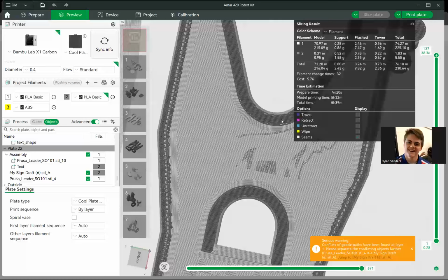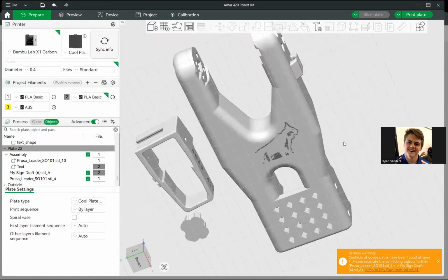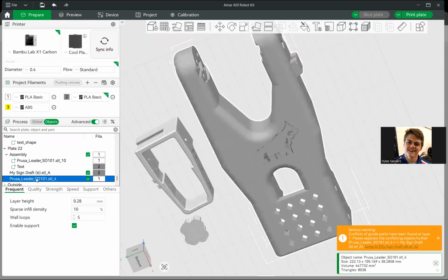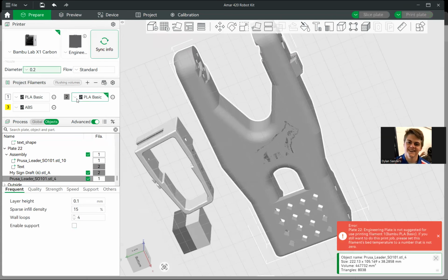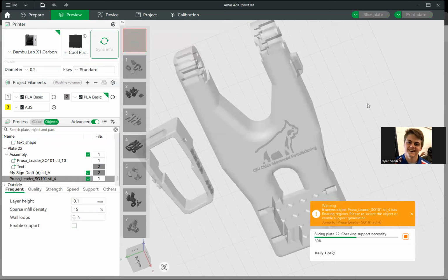And that's because, like I said, it is a thickness thing, right? If you don't make it thick enough, if you don't make this big enough, then you can't really see it because it's based off the diameter of the printer you use. So you could come in here and make this a 0.2 nozzle, right? And now we can hit slice plate again, and we'll see if that allows us to see it, but we probably won't be able to see it anyway. We're gonna try though.